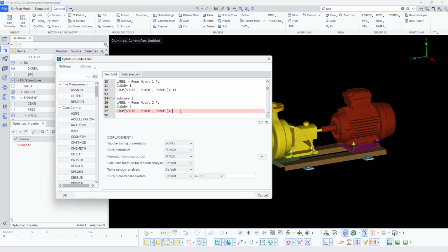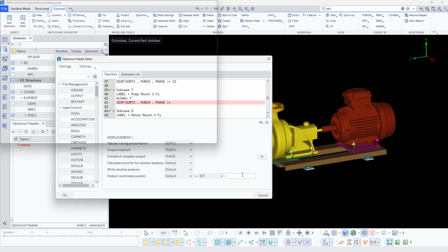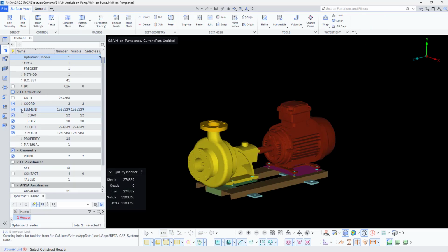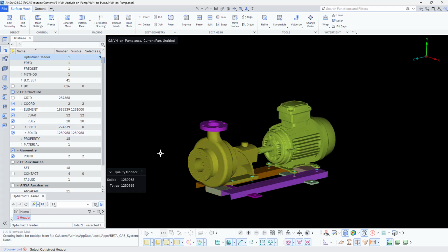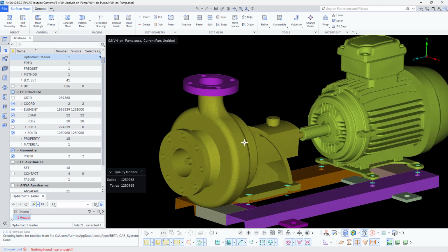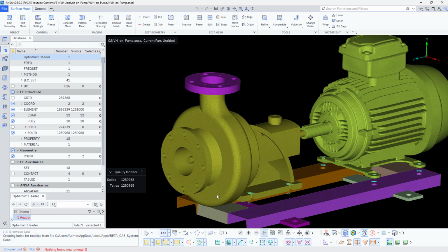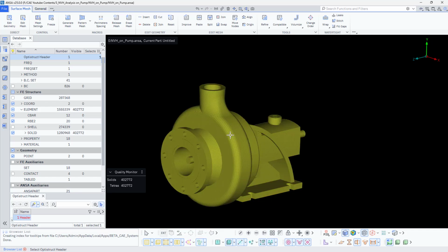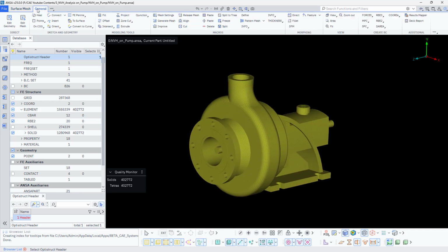For subcases, have you properly selected the sets? The particular DAREA and DLOAD should have the same set point so that it can plot the curves properly. Now I would like to check the weight of it, because I would like to add the self weight in the form of force.